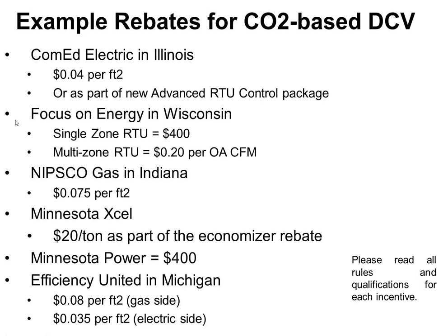When you have a zoning system, it's kind of like some of the examples I showed last week. I need to know if people are moving from one room to the next room. I can't just monitor one sensor, right? And I certainly can't put one in the return duct, because then I'm going to get an average of all the zones. When you have one conference room and 10 offices surrounding it with 10 employees, if they're all in their office and they're breathing and I have a certain parts per million on the wall or in the return duct, that's fine. When they all walk into the conference room together, my return duct is going to still say the same thing, right? But I need to direct the ventilation air to the conference room, and I don't know that they're there because I'm not sensing in each room.